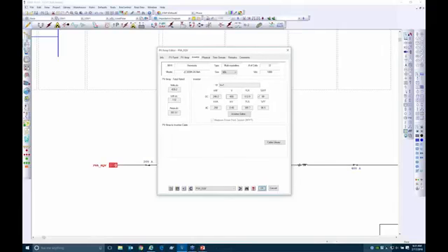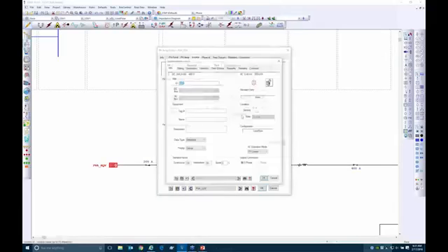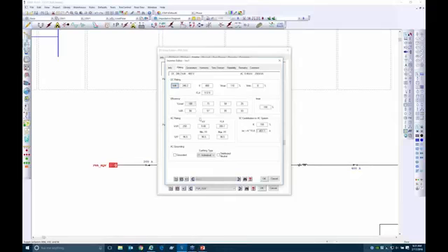And then I can describe the inverter characteristics itself. As I mentioned earlier, it's a 250 kVA inverter at 480 volt AC side, and we plugged in the efficiency at different percent loading. Now for inverters, the efficiency curve is not very dramatic.